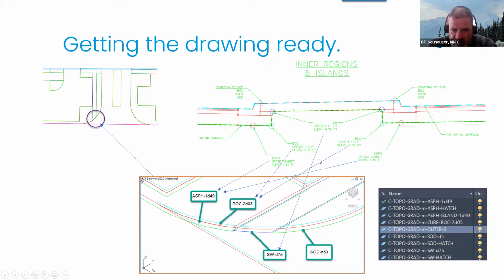So this one here, you can see this is an inner island here, and we've got curb in here. And keep in mind what I'm trying to do here. Now these values that you see here are all based upon your typical section. For simplicity, all I did is I used the box stock curb with the lane, and I believe it's a sidewalk subassembly.